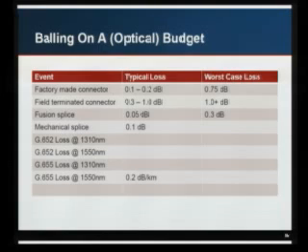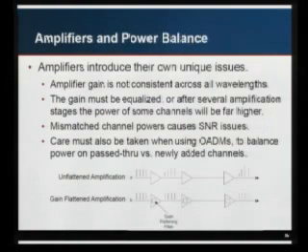When you get out in the field, when you run a cross connect and there's a tech out there field terminating it, and they're doing it with a little kit, and they're using pre-done connectors, and they're just cleaving it and trying to line it up just right, you might see a lot more loss. So you kind of got to budget for more of that. And there's different loss rates for different types of fiber at different bandwidths and different frequencies, and you can find this online.